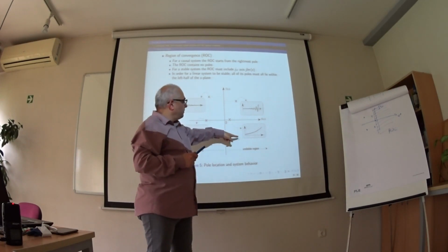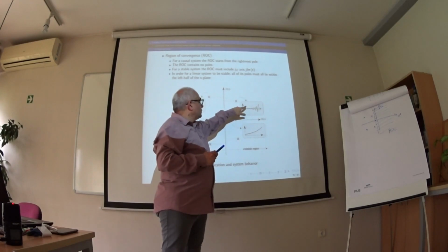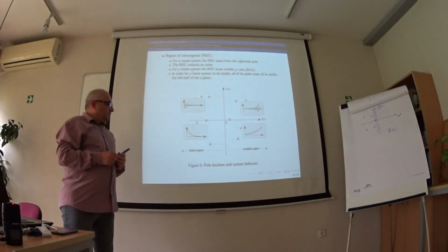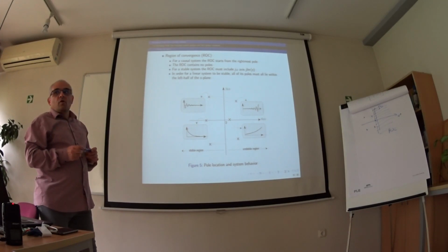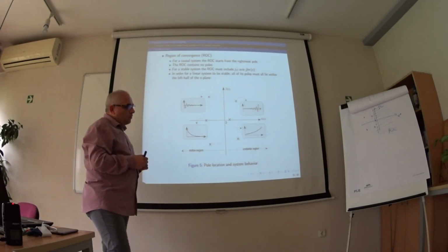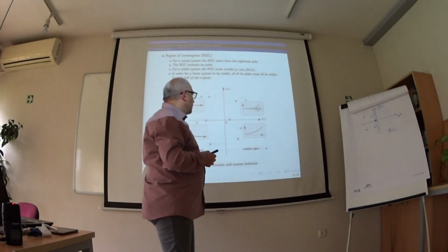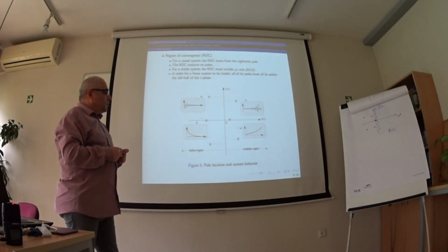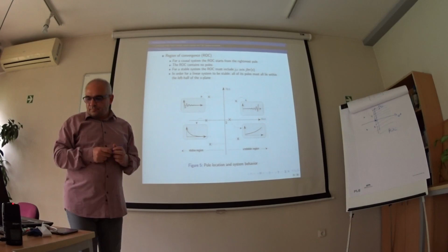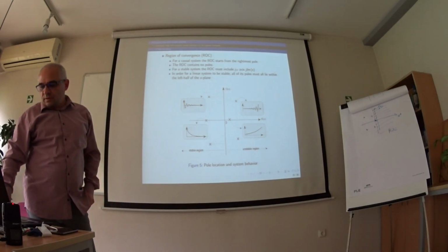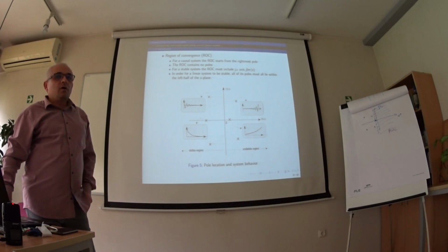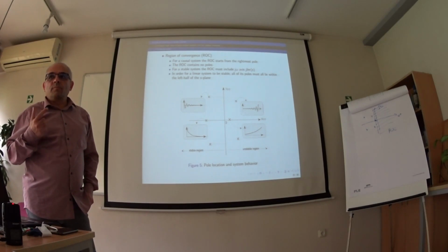You see, we have increasing, no stability. In fact, the poles can be complex or can be real. A real pole, like this, and complex poles, because the differential equation is with real coefficients, every complex pole appears in pair with its complex conjugate.